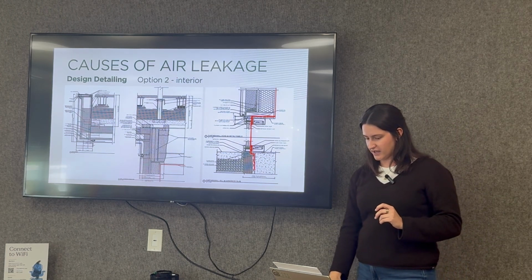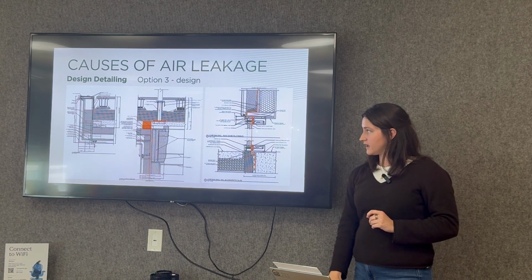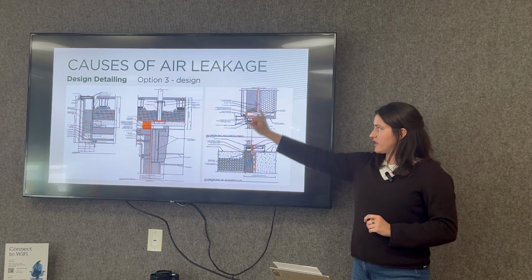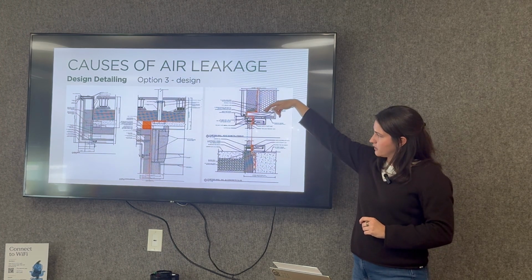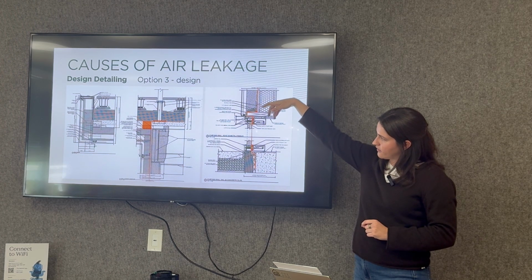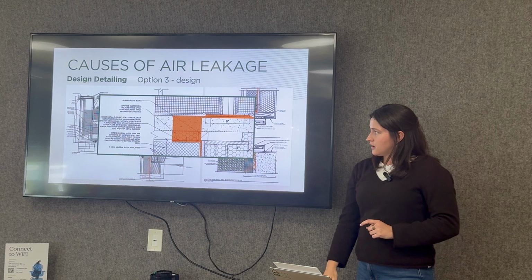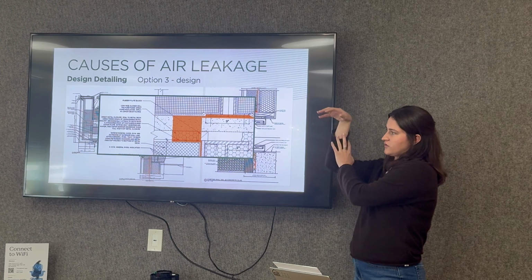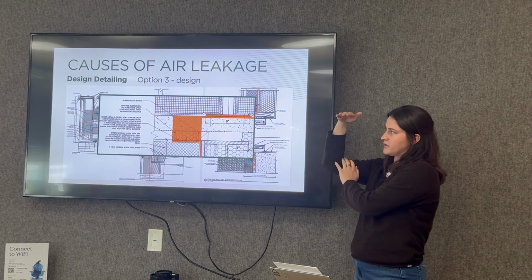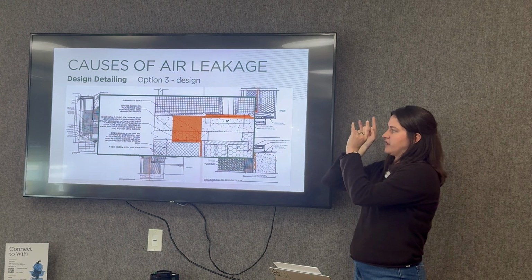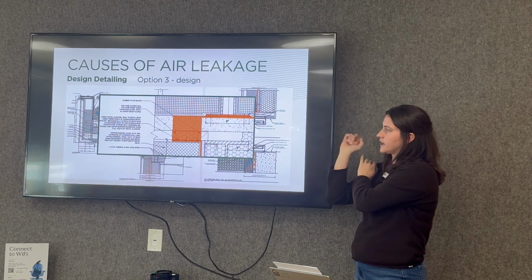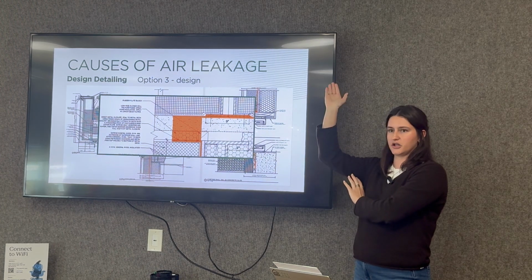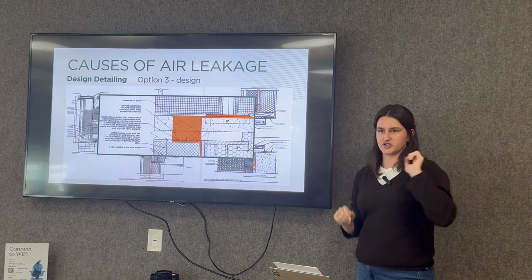What we ultimately ended up doing is having the air barrier follow the same plane up along this way, and then following the vertical line behind the metal panels and the wall. And then we detailed the wall membrane being sealed to the underside of the roof deck. So the lower flutes were filled with spray foam, and then they put a blank off piece of metal with sealant and screwed it up through the metal roof deck. And then we adhered the wall air barrier membrane to that, which gives us that continuity while leaving the soffit unconditioned.